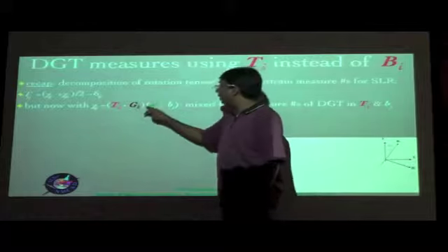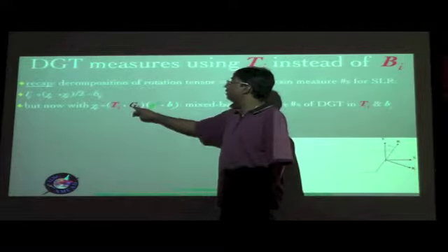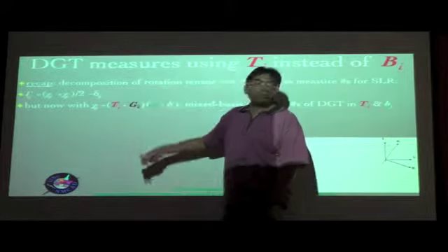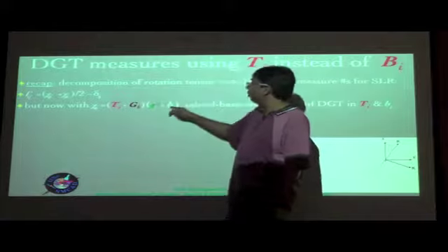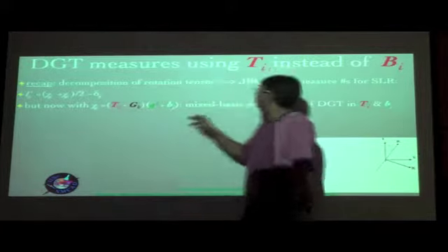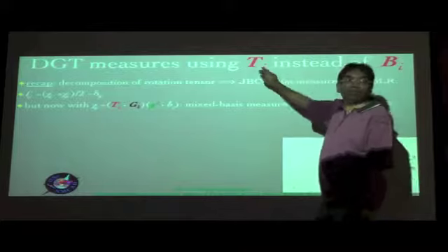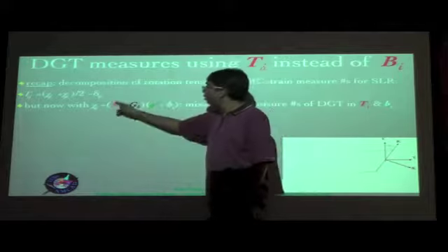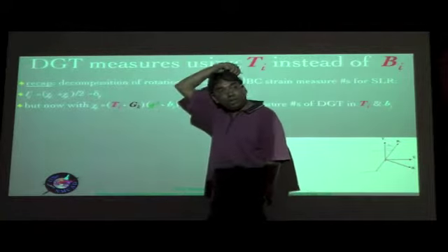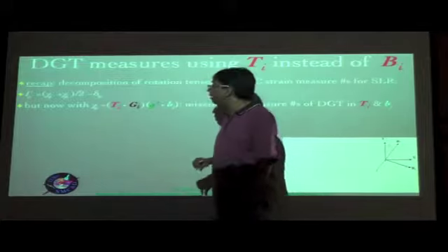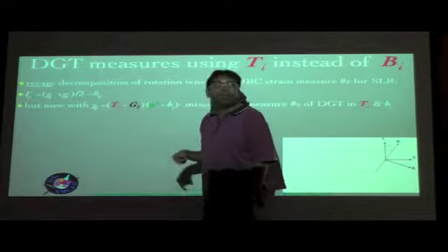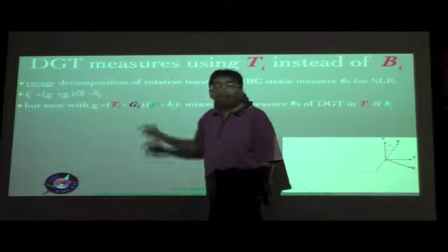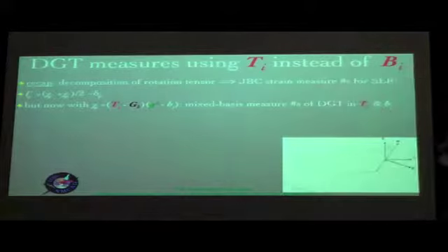Okay, so in other words, there you had still defined the deformation gradient tensor the same way, that is big Gk and small gk juxtaposed with each other, but the way you expanded it out was with respect to the small b and the big B system. Instead of the big B system, now you have the big T system, and so your chi is expanded once again in a mixed basis, but the choice for the deformed configuration, the Cartesian triad that we have, is now instead the big Ti system. So your chi ij will be slightly different because of this particular thing. That is, you have the Ti over there.